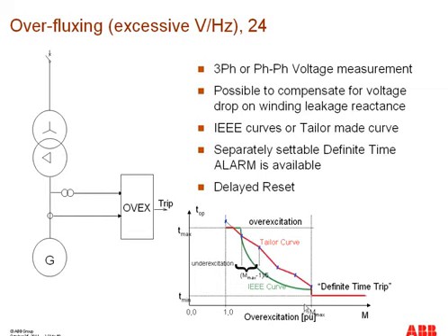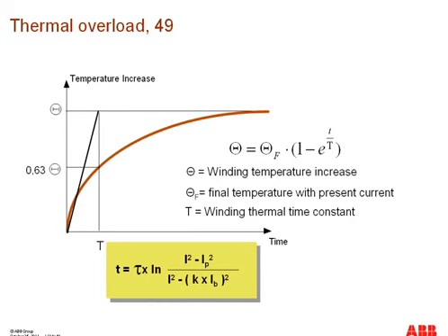Both IEEE curves as well as tailor-made curves are available, and inverse time as well as definite time trip conditions can be implemented for this overfluxing protection.